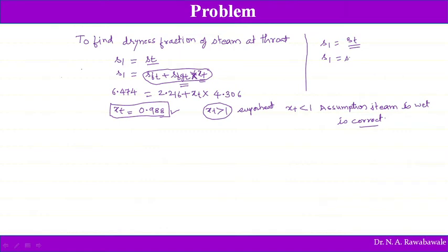That is nothing but Sft plus Sfgt plus Cps natural log of T sup T divided by T saturation at throat. So from Sft, Sfgt, Cps and T saturation T, we can get from the steam table; the only unknown is T sup T. So the temperature of superheated steam at throat can be obtained.